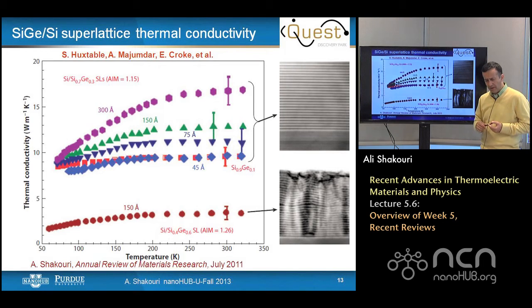One last open problem we discussed had to do with the thermal conductivity of superlattices. There have been lots of theories by various groups that can explain specific results for thermal conductivity for certain superlattice or multilayer materials, based on specular reflection or diffuse reflection and so on. But really there is no comprehensive theory that tells you predictively if you can beat the alloy limit or not.